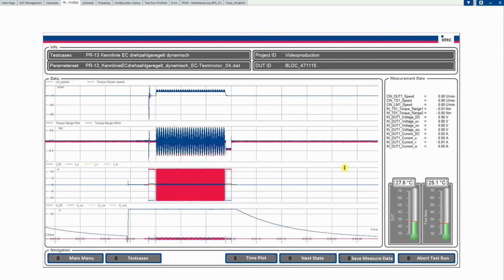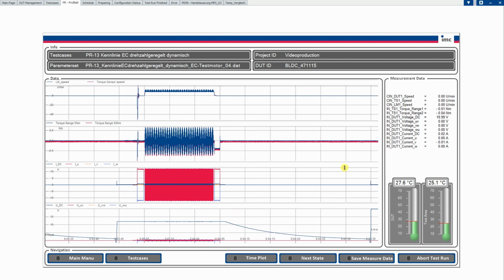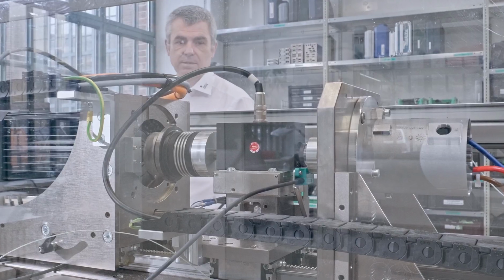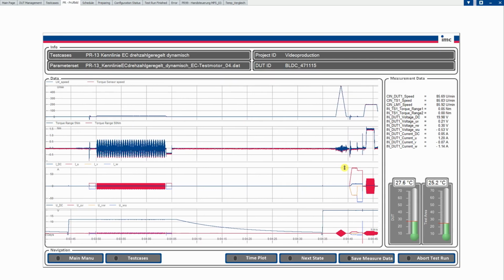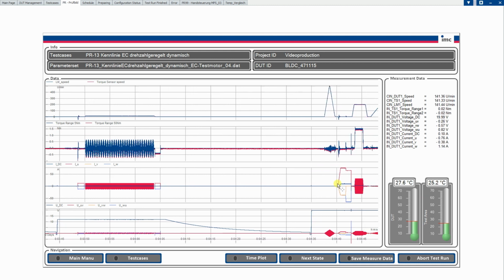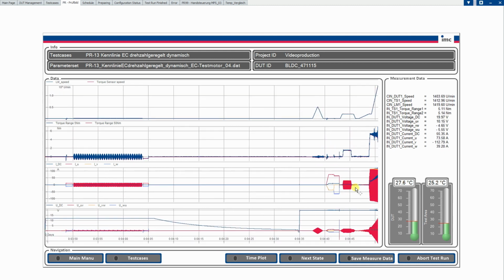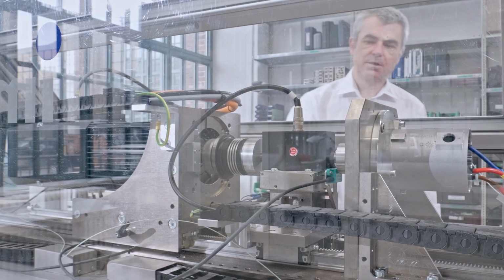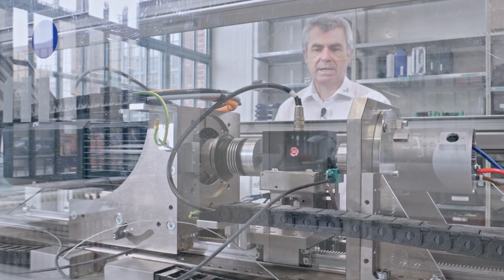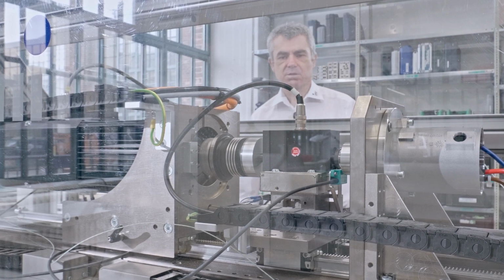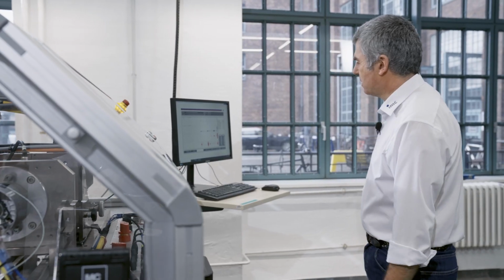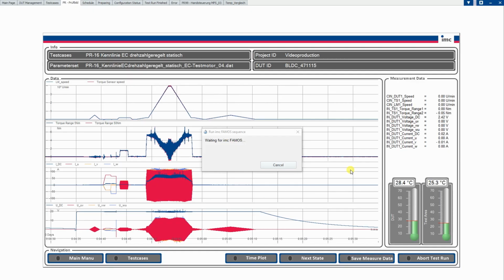which will start with the phasing, a short warm run, and then the speed ramp. So here we are, the test is starting, phasing is done, the short warm run is coming in here in the window. The load machine is running in speed mode and we ramp up and ramp down to the pre-configured speed. Still in braking mode here, stop it, and the test is done.